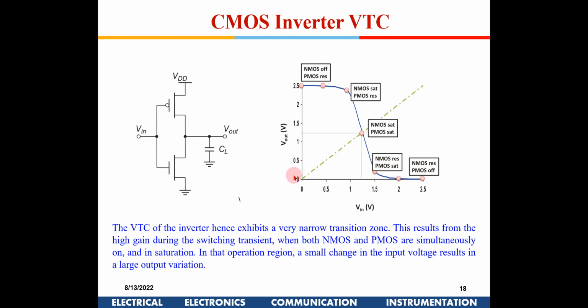Sir, when nMOS is off and PMOS is on, that is operating in the linear region, the output will be VDD, sir? Yeah, it will be VDD because there is no constant current flowing. Initially, this node may not be at VDD, so it will get charged till VDD. Since it is a PMOS, it can pass a perfect one. This output will come up to VDD. Similarly, when the Vin is high, this is a perfect zero transmitter, so it will pull down all the voltage to zero.